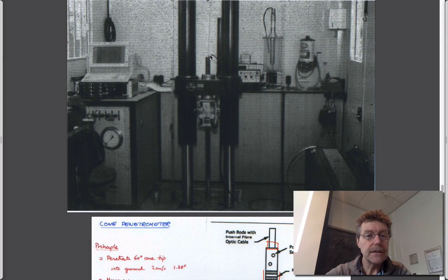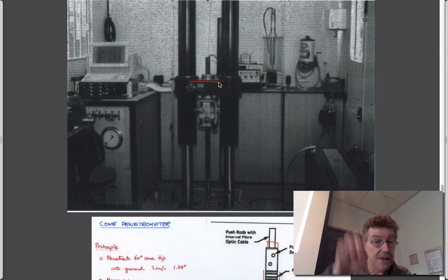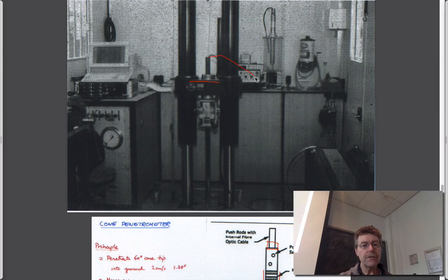It has the load measuring cells and the pressure transducers electronic, so there's a signal that comes from those. And so this is the cord that comes up from them. And as you can imagine, you're going to push this thing into the ground by pushing this down. It'll go down to the bottom of the truck. You'll add another length on it. That length, of course, has to be pre-threaded with this thread.